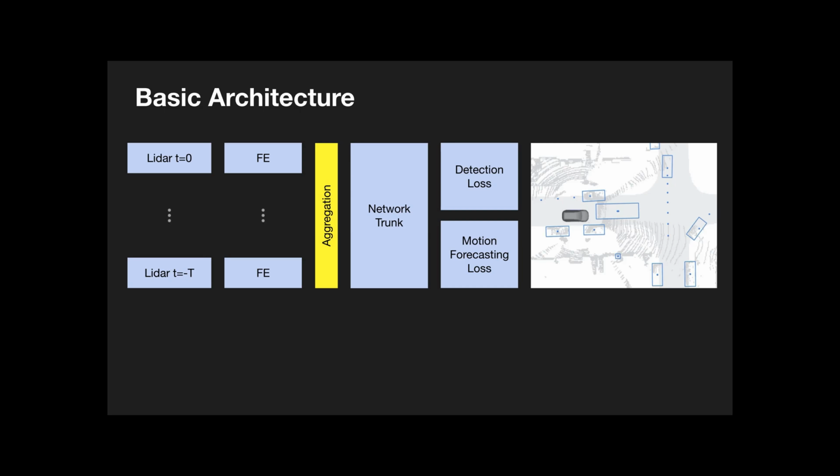I would like to note that this projection step results in some data loss. This is because there's quantization into the cells, and also multiple sensor readings could fall in the same location. So some sort of averaging needs to happen.